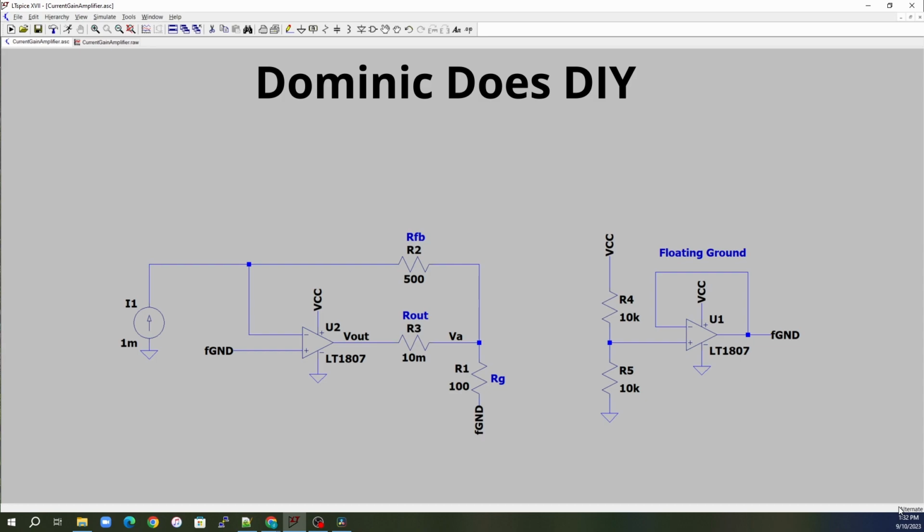That's the video. I hope you learned something from this, or got some information out of it. And that's how we're able to make a current amplifier. Most people use op amps for voltage amplification, not really current amplification. And you would have to find a way to incorporate this current amplifier into your circuit. There are other current amplifiers out there, like you can use 2 BJTs and whatnot.